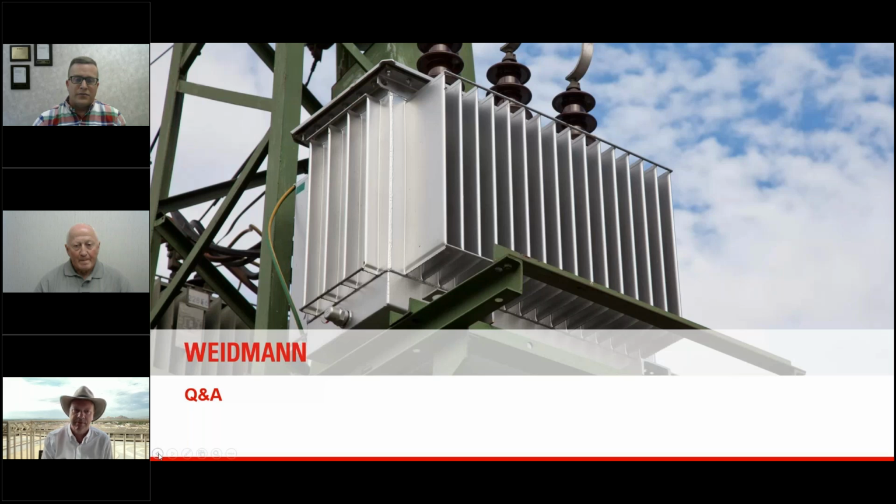In power transformers, the paper that is wrapped around the conductor wire is really the insulation material that is seeing the hottest spot, kind of the equivalent of the hot spot in a layer winding transformer. You have the paper, and so yes, we do have in the works a solution for that. And anyways, we have this example in DPE, and so we're very excited that we can take all of our knowledge and learning about the use of DPE in layer winding transformers and its improved aging, everything that we've learned, and take that to our current developments in a wire wrap paper. So we're excited about the future of that, and there should be some news on that in the near future.